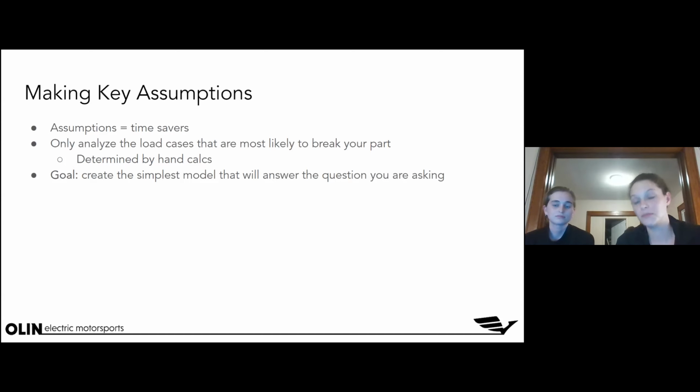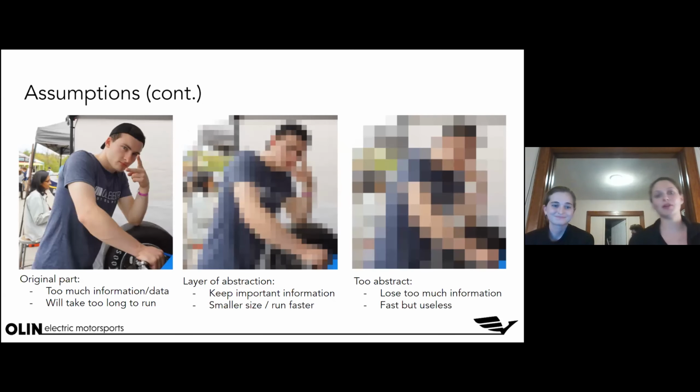So the goal, what we've been talking about right now, is you want to create the simplest model you possibly can that still answers the question that you're asking. A good way of thinking about this is with picture resolution. So Kyle in high def on the left is the original part. It is full complex geometry. But it has way too much information and data. If you were to input all the load cases and everything, it would take way too long to run, and you'd be wading through too many results.